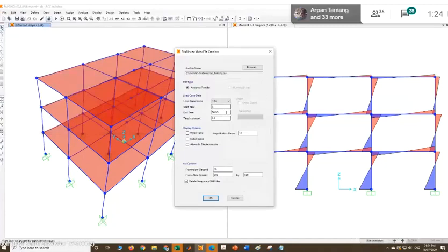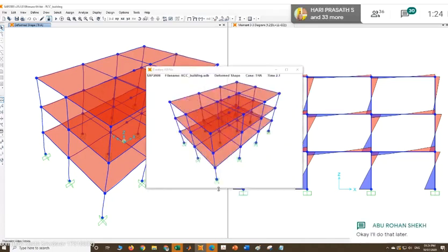Okay, so we will create a video for the time history analysis. Start time is this, and end time is this. We can change the increment if you want to see small variation or large variation. Okay, the magnification we saw as 50,000, right? So yeah, we can see how the building is deforming with the earthquake.